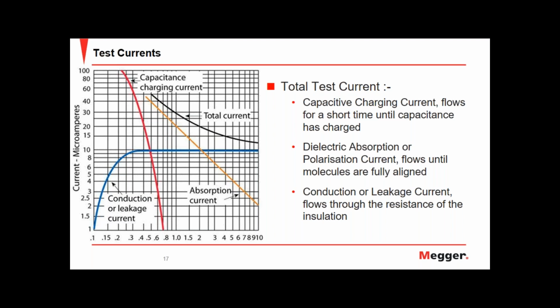So going back to my earlier example where you do a spot test, that's a very narrow look at insulation, you could argue. It doesn't give you a full picture. It only gives you part of the picture. So the more tests you perform, the more holistic you are in terms of the knowledge you have of that insulation material. So by adding the PI and the DAR test into your equation, you're in a better position to assess the insulation material holistically.